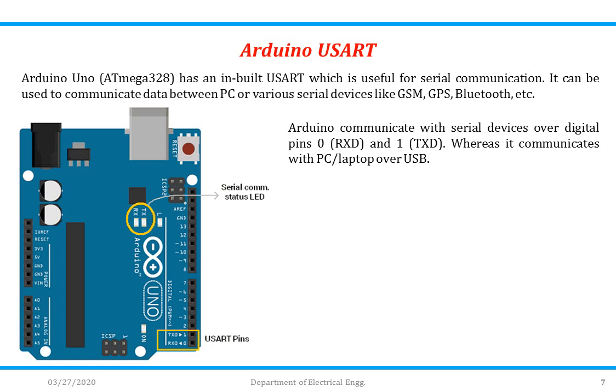For two devices to communicate with UART serial, three wires have to connect them. The first two are communication wires. The transmit, that is TX of the first, has to connect to the receiver, that is RX of the second. And the transmit, that is TX of the second, has to be connected to the RX of the first. Means there has to be a closed loop.